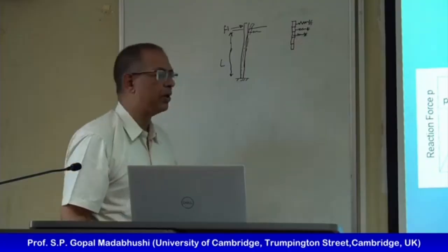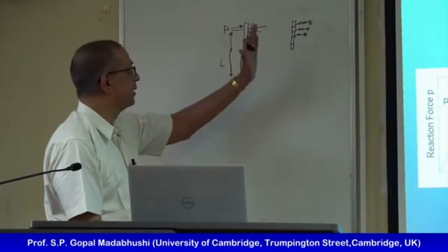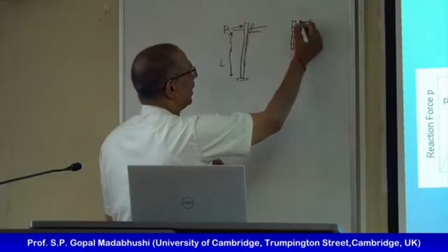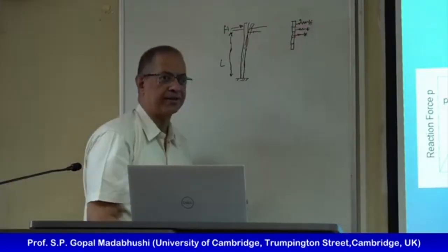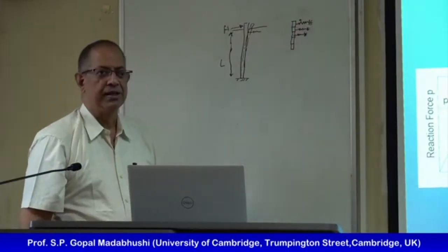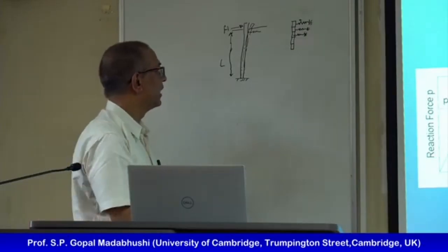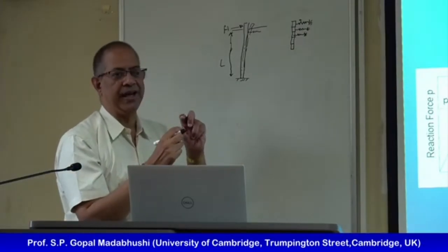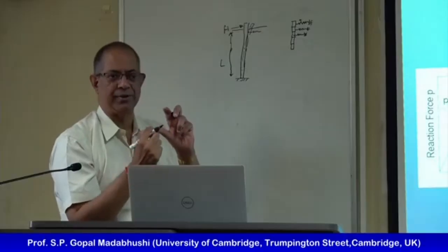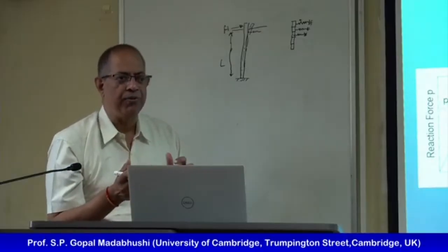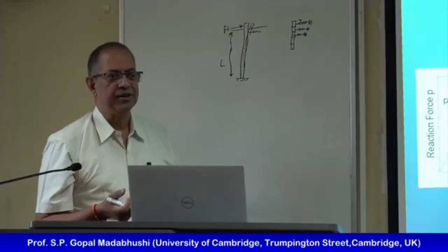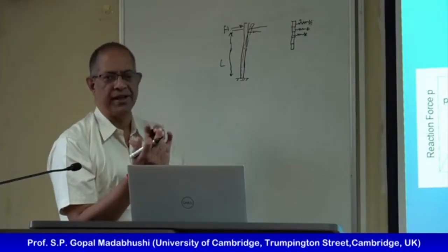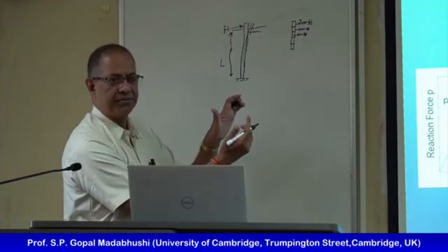Okay, so when I am pushing like this, depending on how much deflection I get, I'll apply a spring force to oppose it. So if I know the force, I can divide that by the area of the element, or projected area of the element, and that will be some form of pressure, right? So that will be the soil pressure generated to oppose the movement of my element.